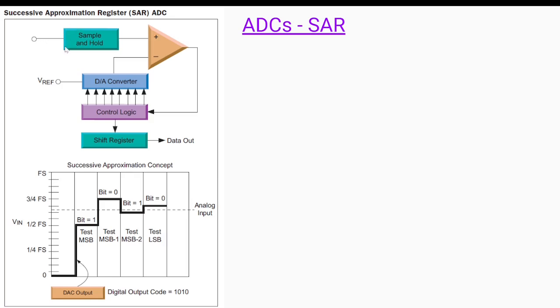Signal comes in from here. This is your sample and hold, and this, which we all know, is basically an op amp or a comparator. Also, we call it a difference amplifier, but here it is primarily used as a comparator so that it can generate a fixed amount of voltage here, and this logic is basically the control logic to send the converted digital voltage to the respective output digital shift register. And that's exactly what's happening.